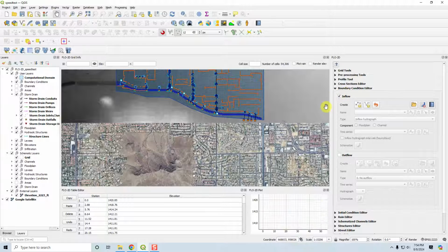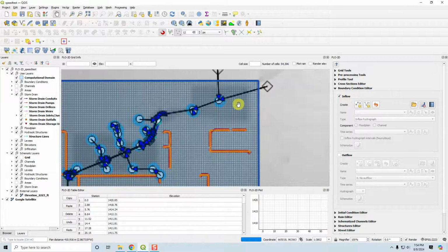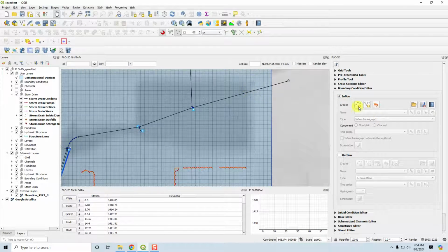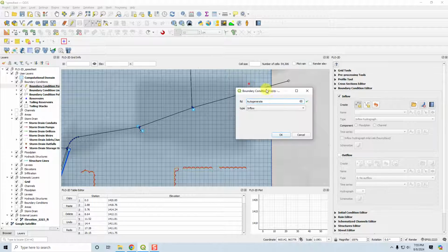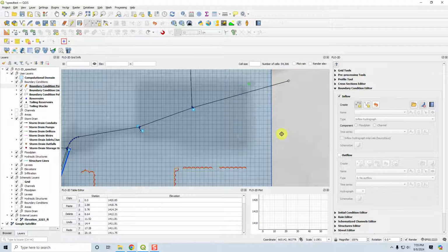So we'll start with an inflow. Let's do a floodplain inflow. We always put one right up here. So you'll click the button and you'll add, you do not want snapping on when you're using inflow. Any of these tools that have to be assigned to a grid element, because you don't want to snap that to a corner. And it will then assign it to 4 grid elements. So no snapping. So you select the point where you want to drop your inflow node, click OK.